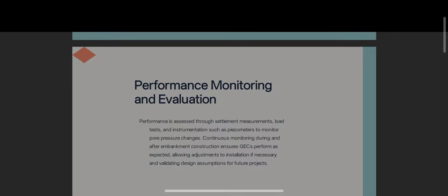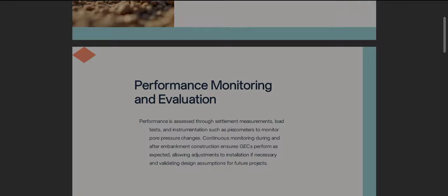Performance monitoring and evaluation are essential to verify the effectiveness of geotextile encased granular columns and to ensure that the improved ground meets design requirements in terms of settlement, stability, and load bearing capacity. Monitoring also provides valuable data for validating design assumptions and improving future projects.